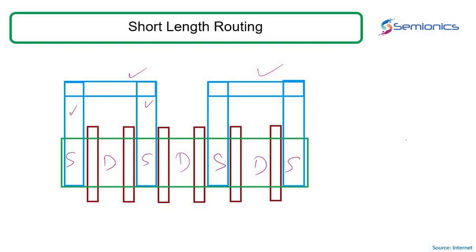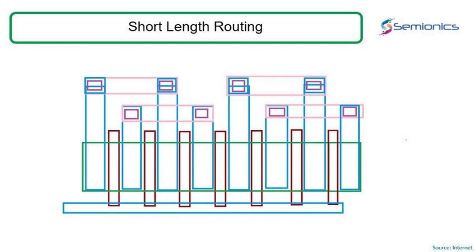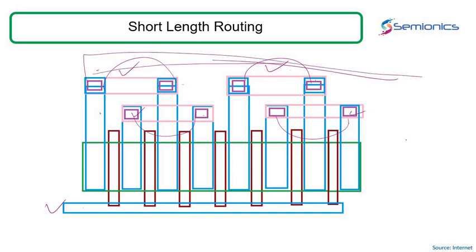Now if I expand this a little more, this is how I would make a connection for two similar terminals over here, and obviously the gate is on the other side. So I'm doing an alternating connection like this. Now I have pulled out wide metal 1 like this and pulled it out to metal 2. Now you might ask, okay, this is open. What you're doing over here is creating shorter connections and pulling the metal to a higher level wherein the Blech length is a lot better. Shorter length, shorter metal.